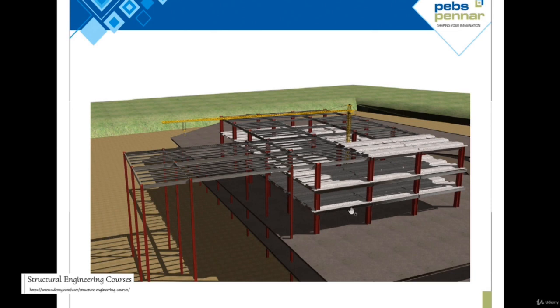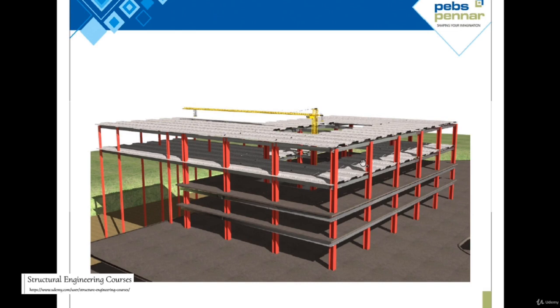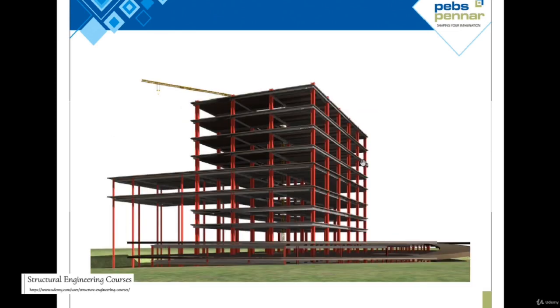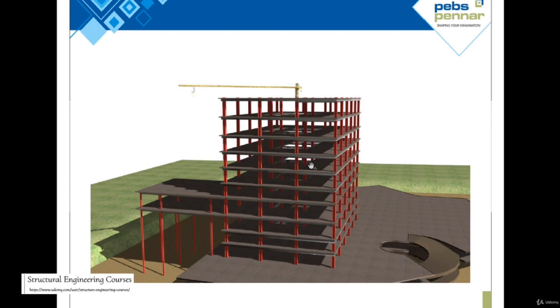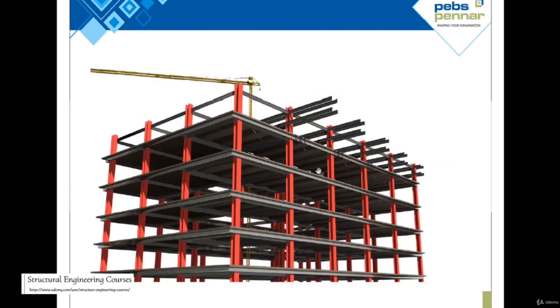And in all these three floors, a live load may act for the worker maintenance or the worker erection loadings. So for this type of arrangement, you need to do various permutations and combinations, and accordingly you need to design the steel structure here. So here you can see that now the concrete has been poured all over the floors, and now the complete steel structure has been built.